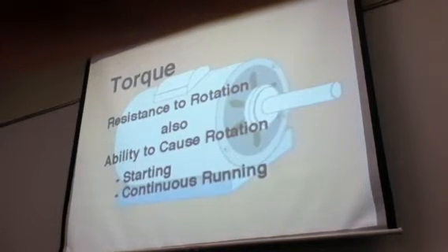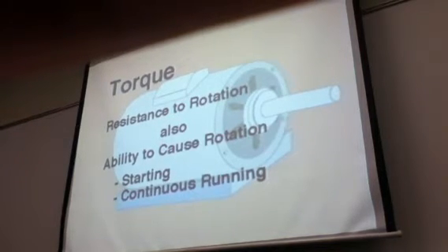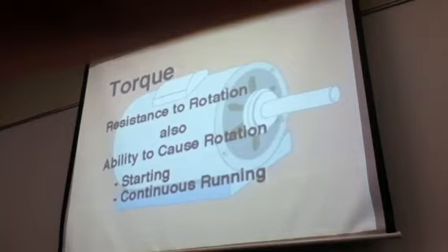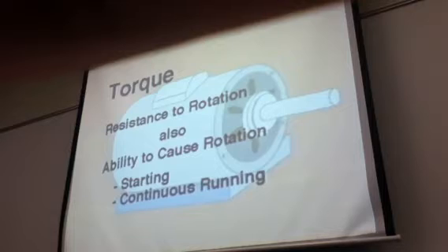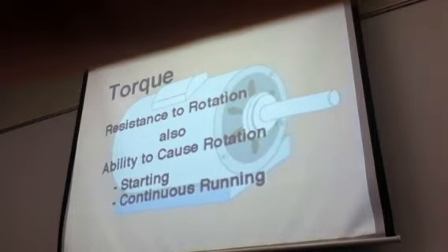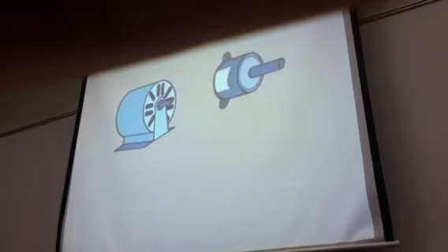Torque is the force that must be generated to turn a motor. A fan motor requires little torque. You can rotate the fan blade with a touch of your finger. A compressor motor, on the other hand, offers a great deal of resistance and therefore requires a higher torque. Also, it takes more torque to start a motor than it does to keep the motor running once it is started. That's why the same type of motor is not used to drive both the fan and the compressor.